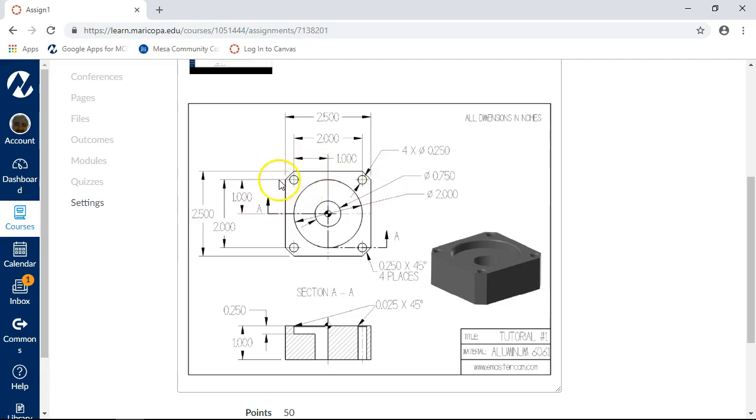And if I put a work stop in the hard jaw of the vise, and again the ergonomics of it, just say that I'm going to hold the vise handle in my left hand. I'm going to pick up the part with my right hand. I'm going to slide it up against the work stop. I'm going to close the vise. I'm going to take the handle off, close the doors, and hit cycle start. And from there, I'm going to watch whatever happens.